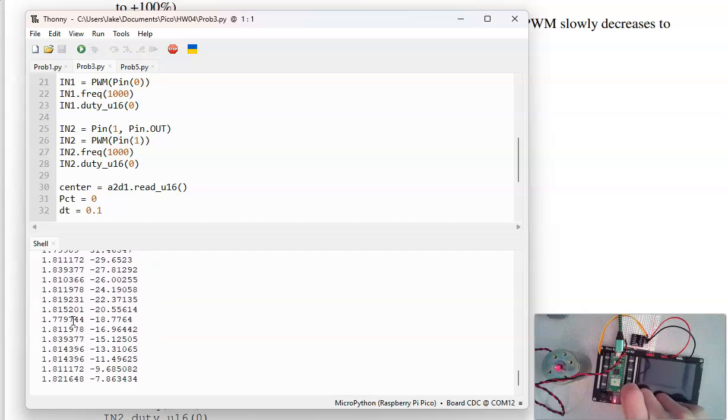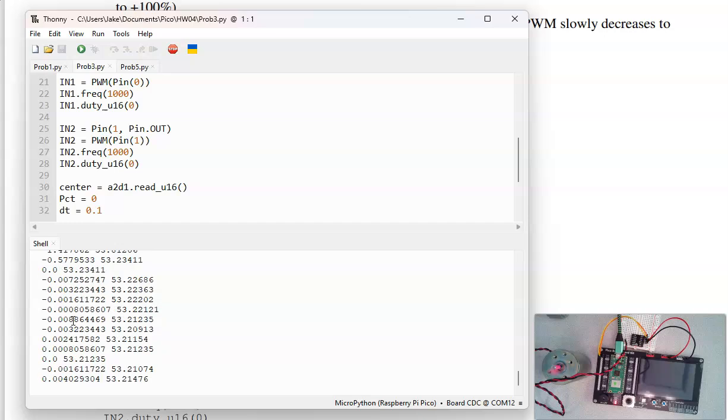So with the analog inputs and analog outputs, I can read the potentiometer, and I can output an analog voltage to drive a DC motor. With the Pi Picos, typically the voltages are output using PWM. I chose 1 kilohertz. Not sure why I chose a kilohertz, but it's just a number. If I change the frequency to something like a...